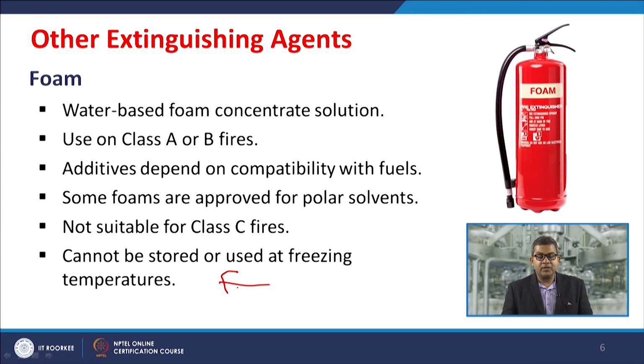Some foams are approved for polar solvents, because solvents like hexane and others may act as a fuel for different classes of fire. They are not at all suitable for class C fires and cannot be stored or used at freezing temperature. So, these are some advisories for using the foam type of fire extinguisher, because ultimately your aim is to extinguish the fire.